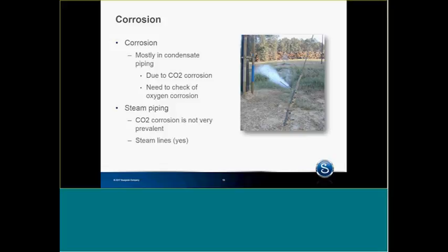So in the steam lines, you should be checking your deaerator for performance of removing non-condensable gases, one of them being free oxygen from the feed water and the makeup water. The standard in the industry, the ASME standard, is 7 parts per billion oxygen or lower.